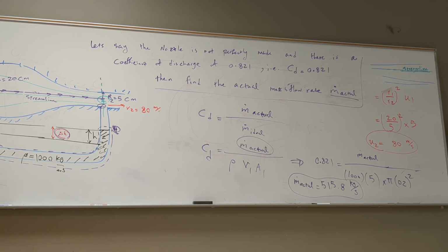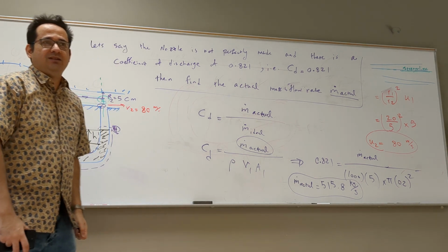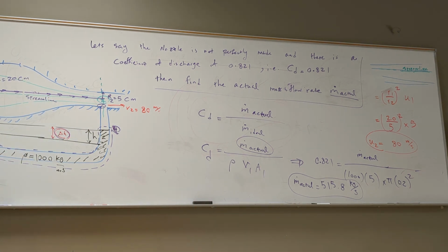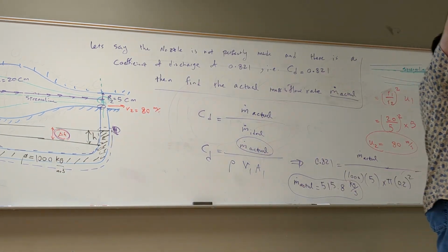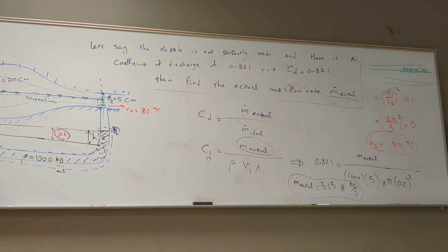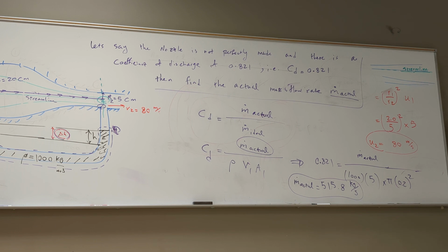Why? Because the velocity is 5 meters per second. That's a huge velocity. That's like running, more than running, like running at fast speed. So that's the reason the height in the previous problem, if you plug in numbers, the height difference in that tube is so huge. That's the reason they put a heavier fluid, like mercury, and even heavier than that. Right?